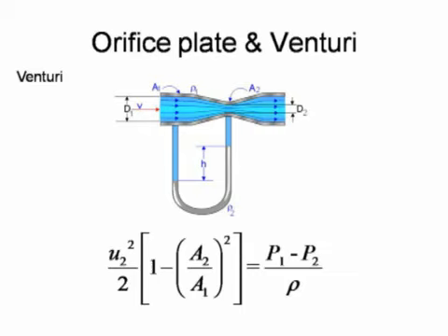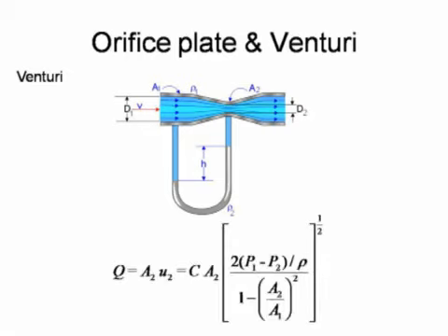While we've rearranged the equation here, having taken pressure over to the right hand side and velocity all on the left hand side, we've made our substitution removing u1, having used continuity. So on the left hand side all we have is velocity in terms of u2, the velocity at the constriction. And now we've rearranged the equation so that, having obtained the velocity u2 on the left hand side, if we multiply it by the area, that gives us the total volumetric flow rate.